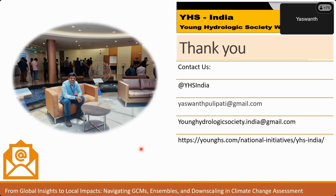And recently, instead of downscaling from 100 kilometers to 25 kilometers, researchers are also interpolating the 100-kilometer GCM data to 25 kilometers and then doing the bias correction, and they say this is working better. So I will directly use this as an input to the subsequent models. But how physically feasible it is should be checked in your region with calibration and validation before using it for application purposes.